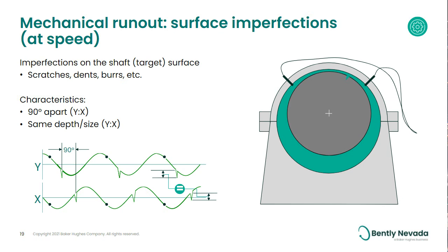As that vibration changes, and as the shaft goes through resonant speed or something like that, how that scratch adds with the vibration can change. So the response to that scratch, or the overall vibration that we see with that scratch introduced, can vary depending on the shaft speed and the shaft condition. So this is where things start to get tricky, and this is where things start to get challenging.